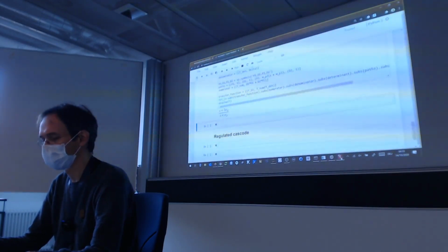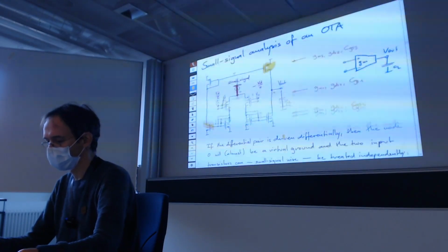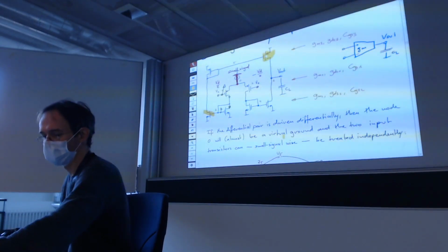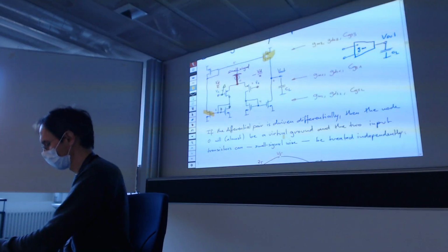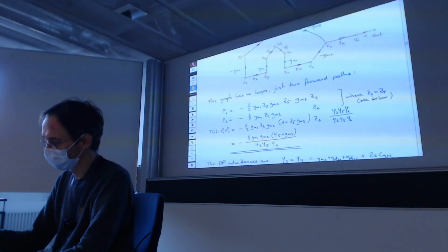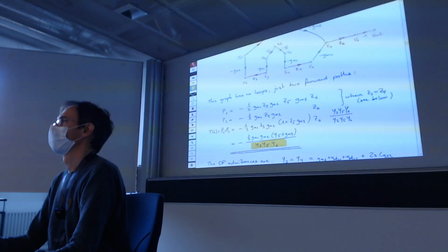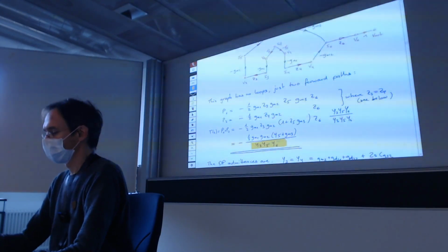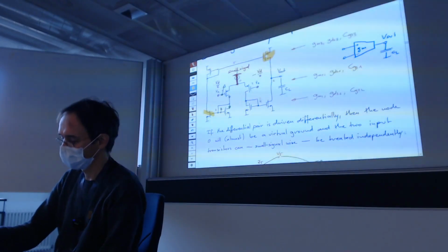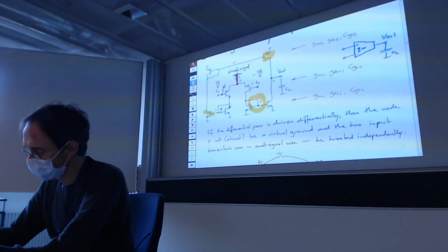And that is what you read in many textbooks which do not use the signal flow graphs, that people will give you the ad hoc method of saying, yeah, please go into the circuit here and look at all of the nodes. The thing you should have realized by now is that if you do the first analysis, all of your driving point impedances will appear in the denominator. So what most analog designers do is they say, okay, I look at the situation at this node.